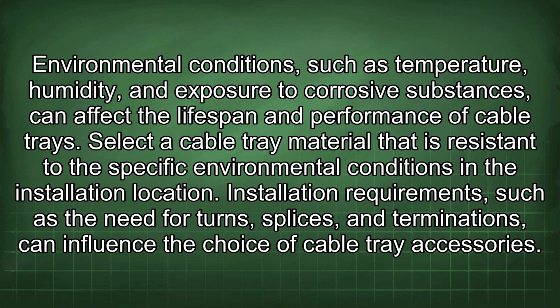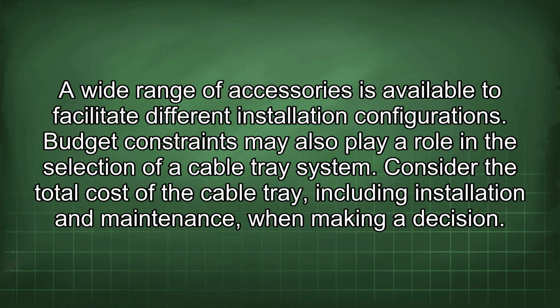Installation requirements such as the need for turns, splices, and terminations can influence the choice of cable tray accessories. A wide range of accessories is available to facilitate different installation configurations. Budget constraints may also play a role in the selection of a cable tray system. Consider the total cost of the cable tray, including installation and maintenance, when making a decision.